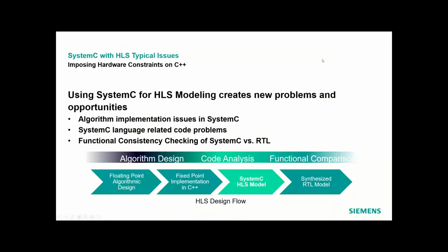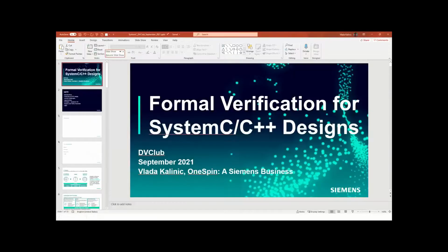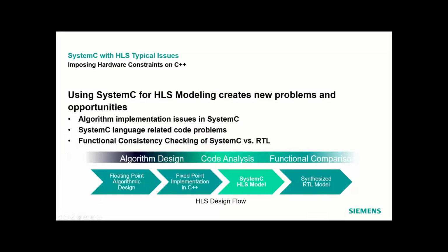Okay, so let's start with SystemC. In SystemC today, SystemC is mostly used for HLS modeling, because with SystemC, as it is one level above in abstraction of your design, you can resolve some problems much more easily, writing some kind of mathematical operations, design types and similar algorithms, than with regular RTL like VHDL or Verilog.